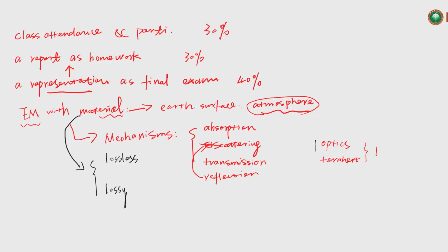We're going to use the lenses to get a higher gain, or to make the beam size smaller and more directional. The lenses usually use Teflon or HDPE, something like that, because such materials are usually considered lossless. We just want to use them to focus the beams, and do not want them to exert any absorption losses on these electromagnetic waves.